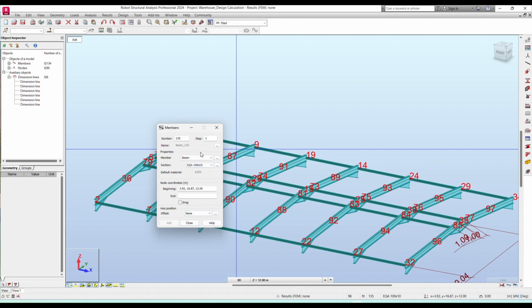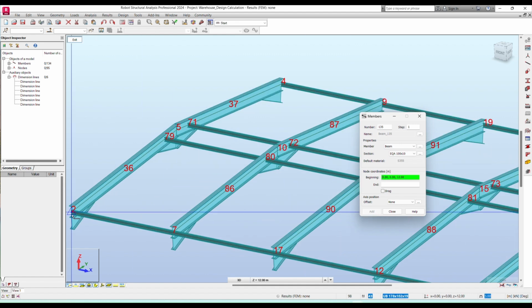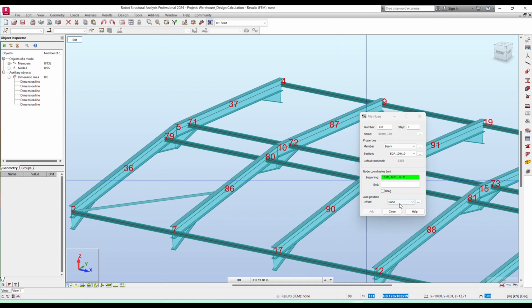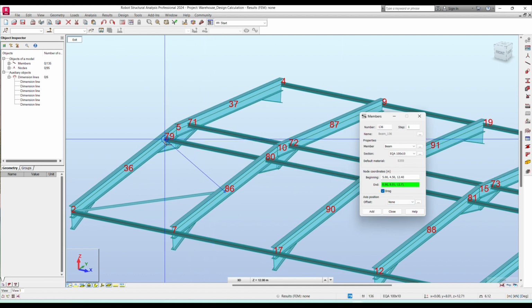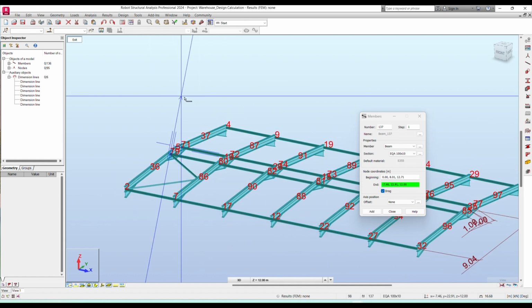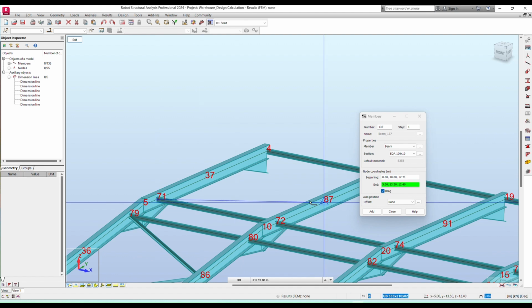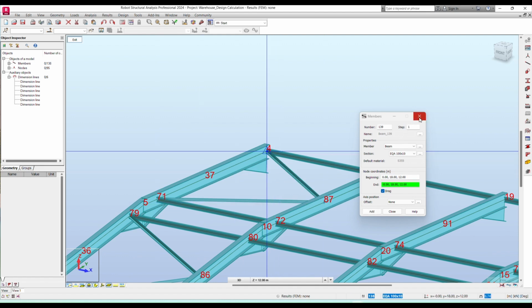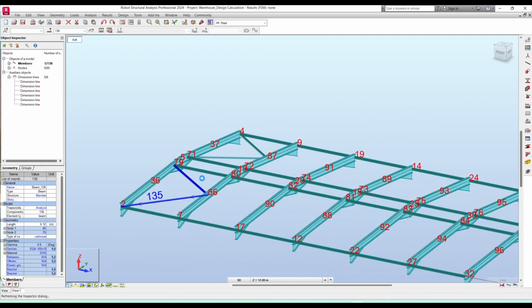Select angle member. Now here we need to draw this. Select drag also, so that the continuity will be there. So we are adding the V bracing here. We can copy and paste it until the mid bay.